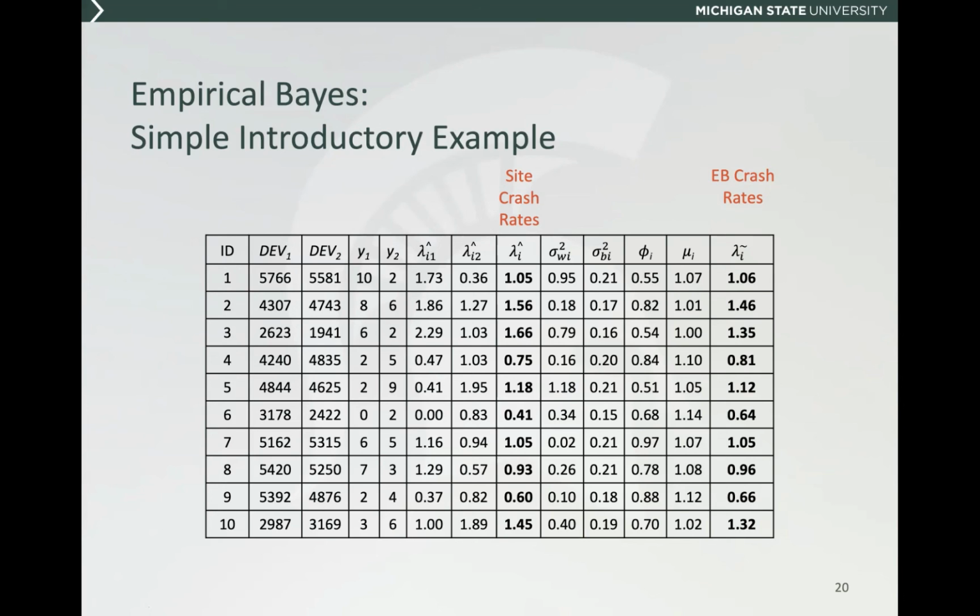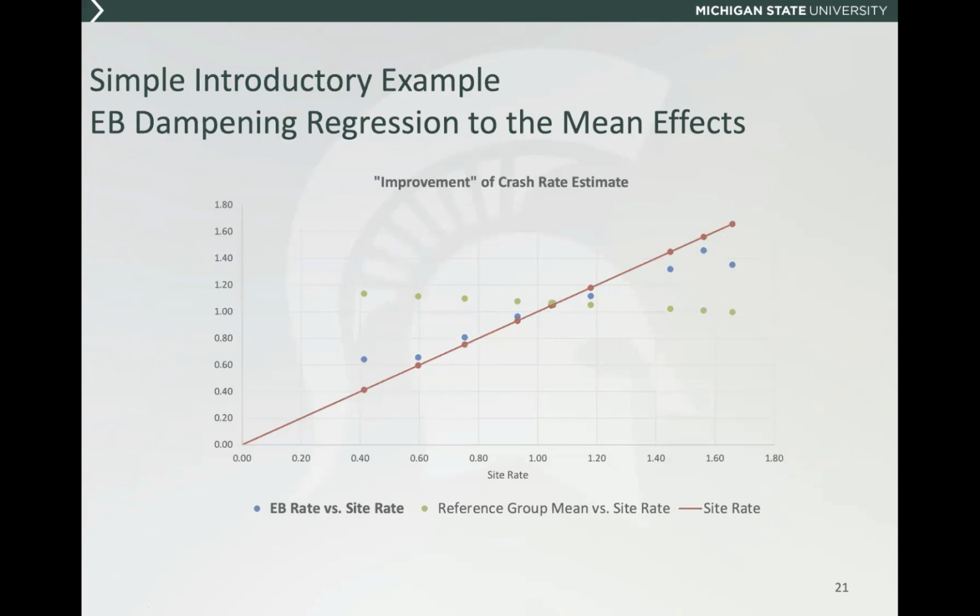And so as an example, if we think about the speed limit increase example we talked about previously, maybe we had selected sites that had low numbers of crashes at which to increase speed limits. And so consequently, we may be underestimating the number of crashes during the period before those increases went into effect. And so the EB method can account for variations in either the higher or lower extremes, as the case may be, okay? And so this plot here basically just demonstrates our site-specific rates.